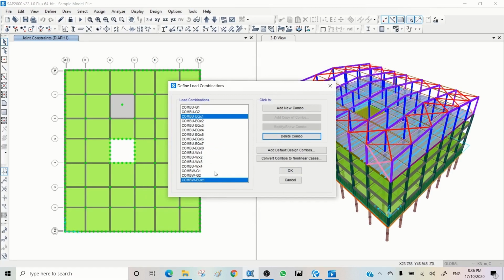What we need to do for serviceability. Serviceability is different from working stress. In working stress, the ratio between ultimate and working stress is always 0.67. Serviceability goes back to the return period of earthquake or wind. For example, if your annual probability of exceedance or return period for earthquake based on the importance factor is 500 years, for serviceability it could be 25 years or 50 years. So based on that 25 years, you may end up with a different earthquake factor. The factor doesn't have to be 0.67, could be 0.2, could be 0.3, could be 0.25, or any other factor like that. The same for wind. It's not exactly 0.67.